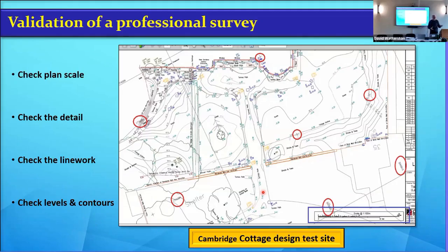I don't know if you've ever seen any of these facial recognition systems where you see somebody's mugshot and then you get all the triangles all forming over it. Same idea as it happens. So they force it that the triangle bases are all around the break lines. Then the contour has got no way but to go nice and straight across there. So I have manipulated bits of this that I think are reasonable to give a representation of the ground.